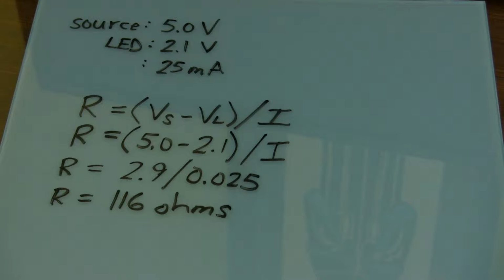So what the book tells us is that if we have 116 ohms of resistance, then the circuit will be perfectly balanced. Now, it also says that in most kits, you won't find that exact type of resistor. The next one up that you're likely to have is 120. Unfortunately, I don't have one of those, but I do have 220. And the book goes on to say that it's okay to have more resistance than the ideal amount. And it says suitable values from various kits would probably include 220 ohm, 330 ohm, and 560. So I have 220, that's what I'm going to use.